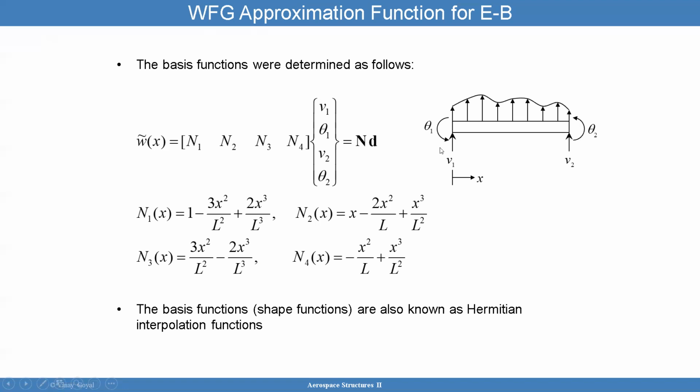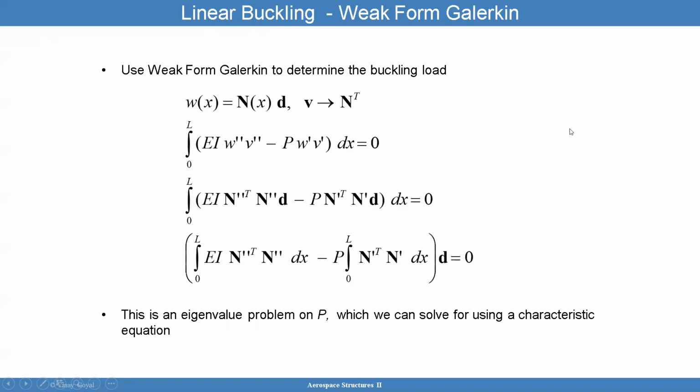Oh, and I had the picture here, I'm sorry. So this is the beam, and these are node number 1 and node number 2. Remember, every element is going to have nodes that describe the domain, the subdomain. And here, the nodes for the beam are here and here. So I want to solve for the values at those nodes.